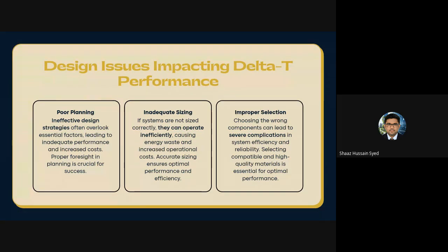And if you place your differential pressure sensor in the wrong place, I've seen this issue in many projects. If you place it near the pumps, it will think that it needs to run fast when it doesn't. Too much water is flown, and then the delta T collapses. This is again a reason related to the design.